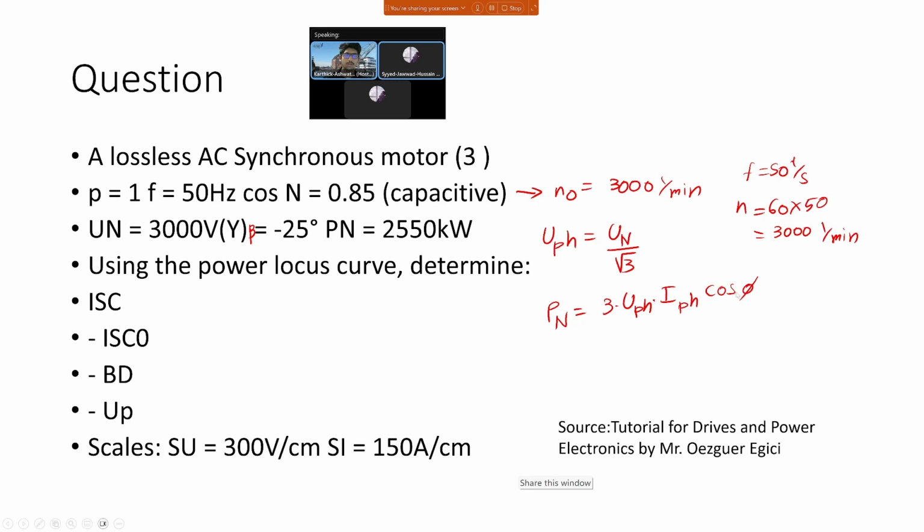And it will be nominal speed. This is like always. There is no nominal, no breakdown speed. It's always at this speed. If the frequency is the same, it's going to be at this speed, irrespective of what load there is, until you stop it. Basically, like that's the short circuit case. So any load which is below its breakdown torque, like the maximum torque it can give, it will be running at this RPM. So that's the special thing about synchronous motors. So they are not having the self-regulating feature which asynchronous motor had.